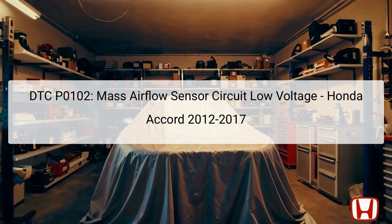Today we will be discussing a specific diagnostic trouble code, DTC P0102, which indicates a low voltage issue in the mass airflow sensor circuit for the Honda Accord models from 2012 to 2017. The mass airflow (MAF) sensor is crucial for measuring the amount of air entering the engine, which aids in determining the correct air-fuel mixture needed for optimal engine performance.